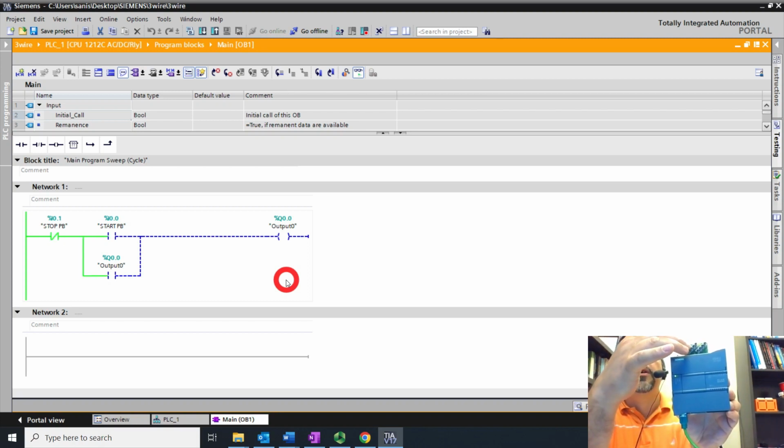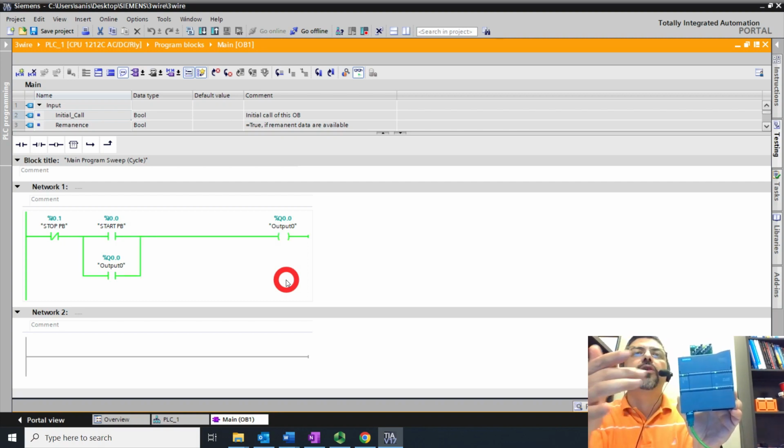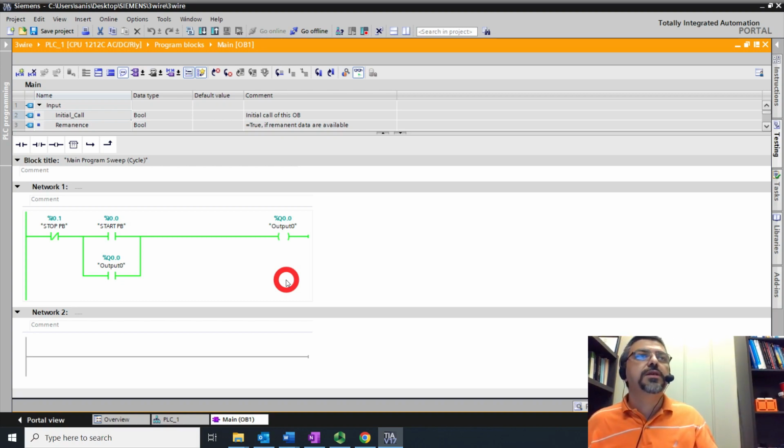The other thing you could check: I start the motor, and it is working. Even as you could see, if I release the start button, it's still working. So the only way you can stop it is to push the stop button. Definitely, whenever the stop button is pushed, even if you turn the start on and off, it is not going to work, right? So you need to release the stop button, then you are able to turn on your motor, as you could see here. So as you could see, we implemented and downloaded it on the PLC.